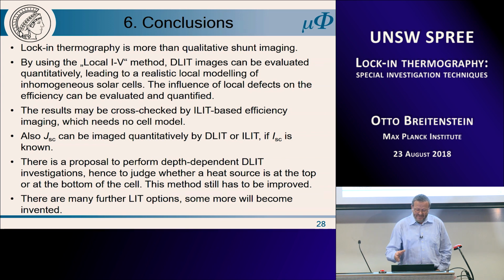Also, JSC can be imaged quantitatively both by dark and illuminated lock-in thermography, and there is a new proposal to perform even depth-dependent DLIT investigations, hence to judge whether a heat source is at the top or at the bottom of the cell. However, this method still has to be improved. There are many further options for lock-in thermography, and I'm sure that some more will be invented in future, and I'm looking forward also here to contributions from UNSW.